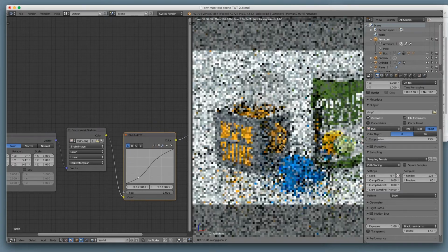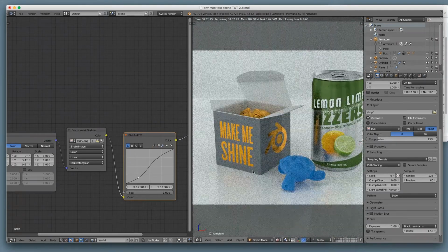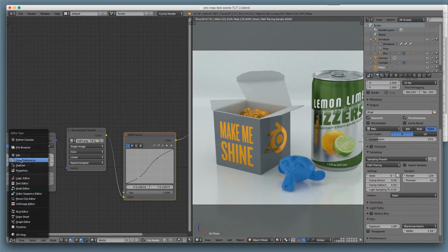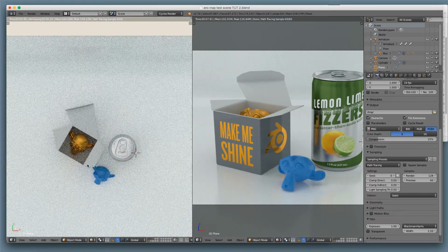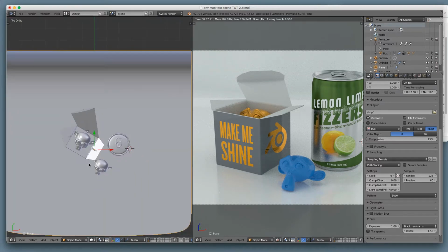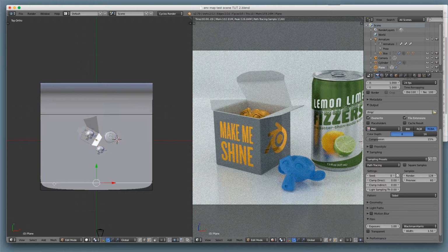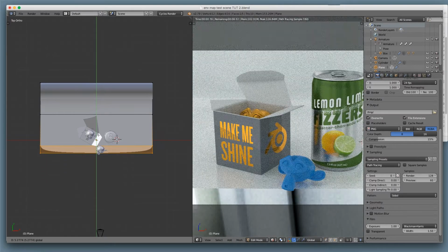let's bring it back a little bit here. You probably want to rotate the environment. What I'm actually going to want to do here is the cyc is really, really large, and it's kind of kicking back. There's some reflections going on here that are ruining that. So I'm going to go into 3D view here, go on the top, and edit this cyc. And I'm going to bring this in so we're not reflecting quite.